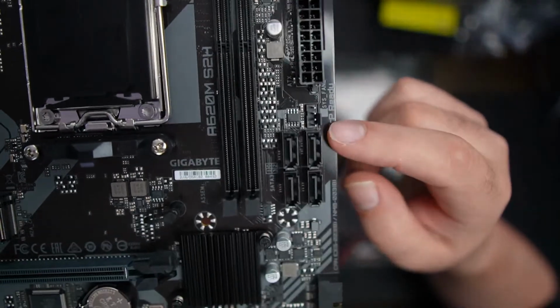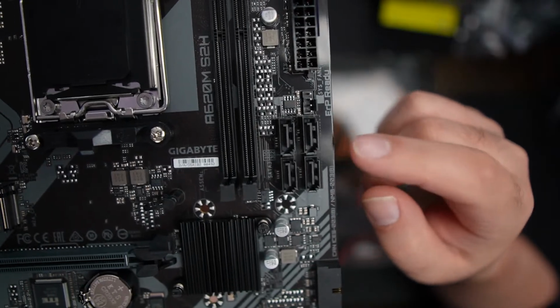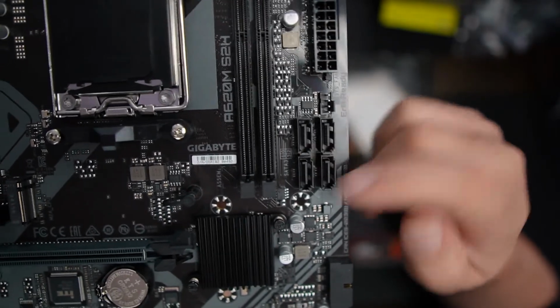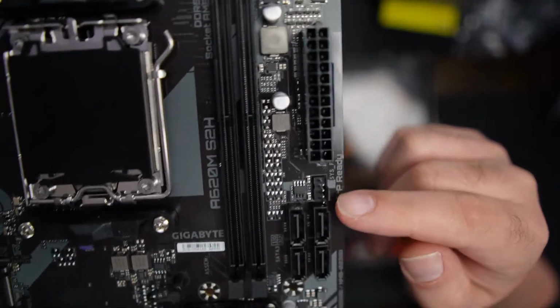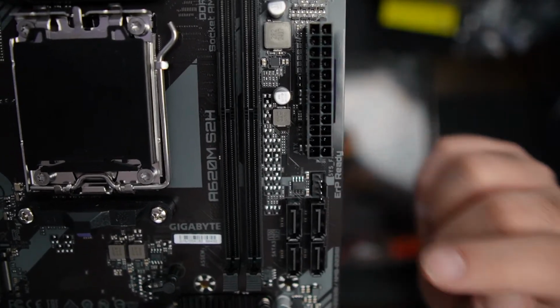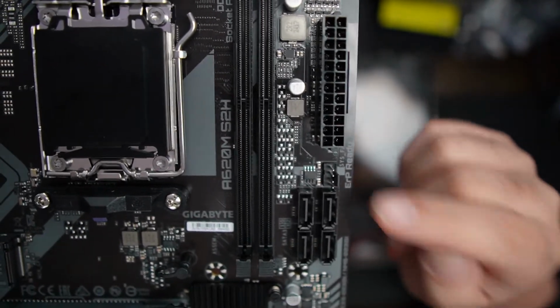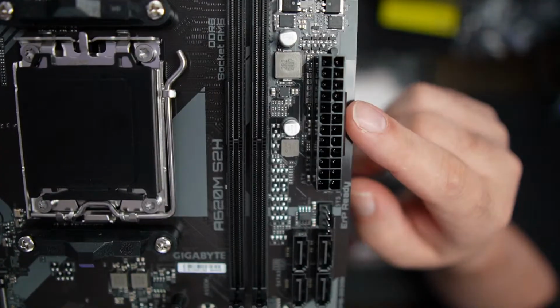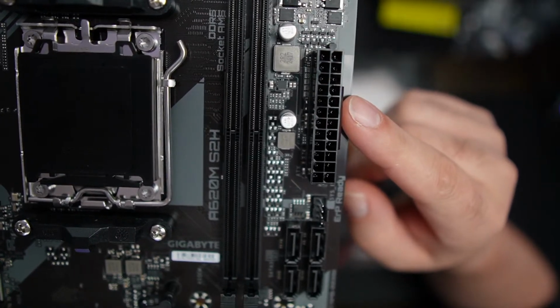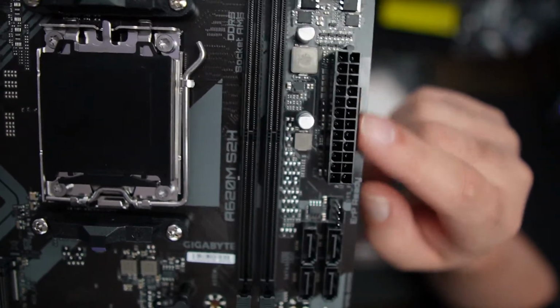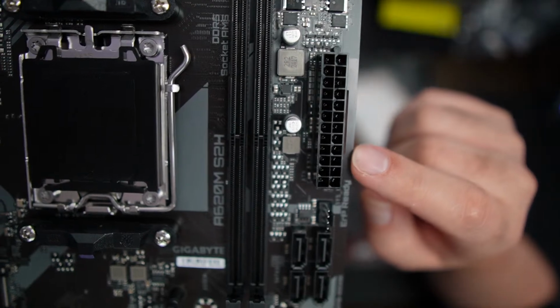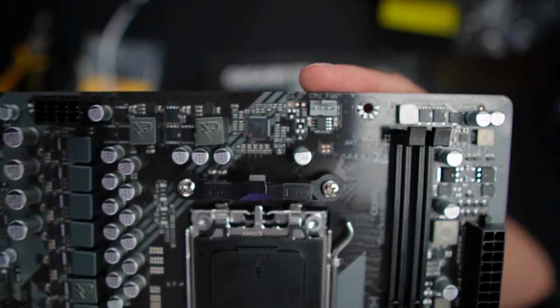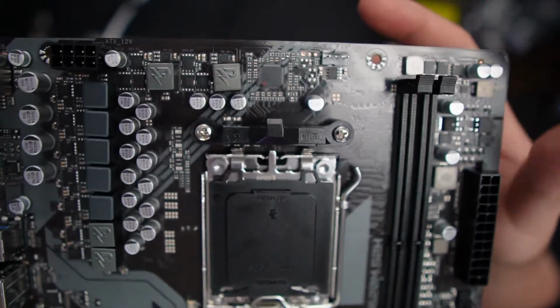Moving further up, SATA connections, which we're not going to be using today, but if you want to add any SATA hard drives, you have the ability to add 4. Another system fan connector, which is 4 pin, but you can plug a 3-pin into it. Any of those 4-pin, you can plug a 3-pin into. Regular 24-pin connection for the power supply, which goes right here. It has a lip on this side, which is where the clip will go when we go to plug it in. Further up, we have the CPU fan. It is labeled CPU fan. It is also gray, so you know that that's the one for the CPU fan.